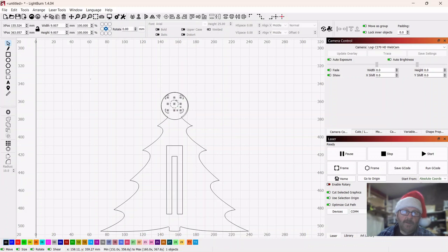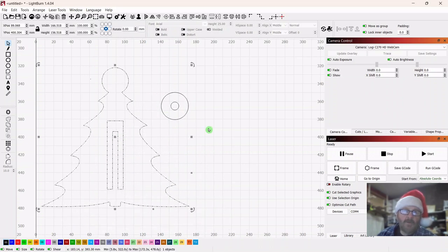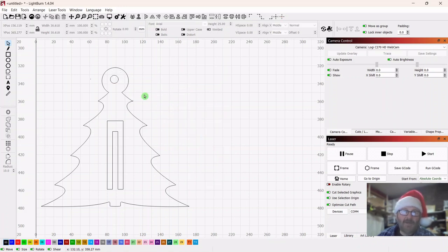Then you could select this circle, select the circle you just drew, and then do a center, a bullseye on. And then you'd have to get rid of that other circle. But it's probably better just to put it up there. But if you really needed to be precise, at least that's a way to do it.